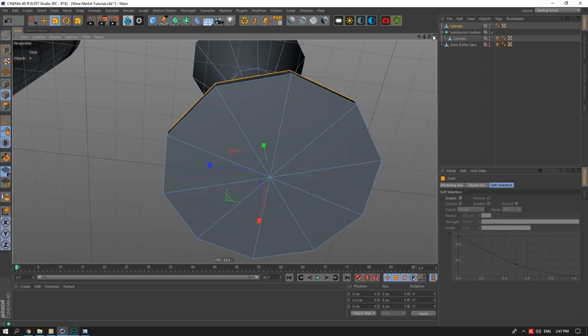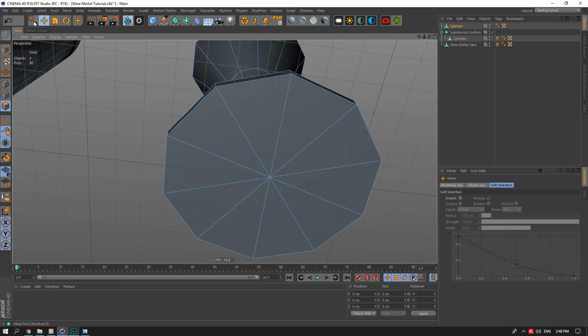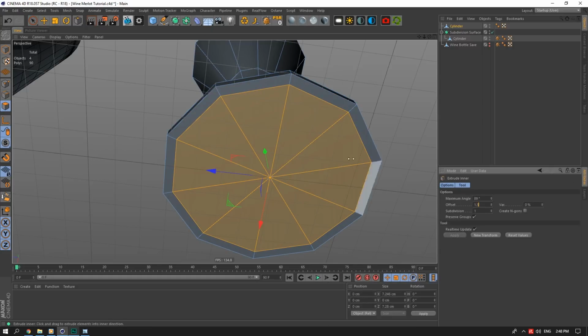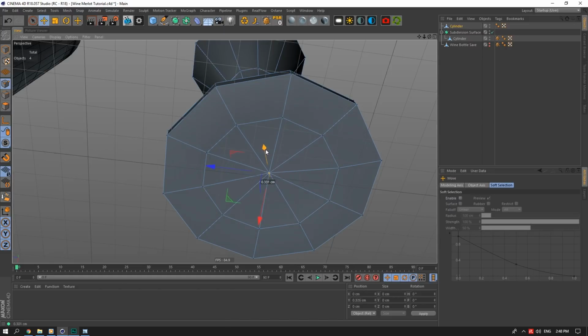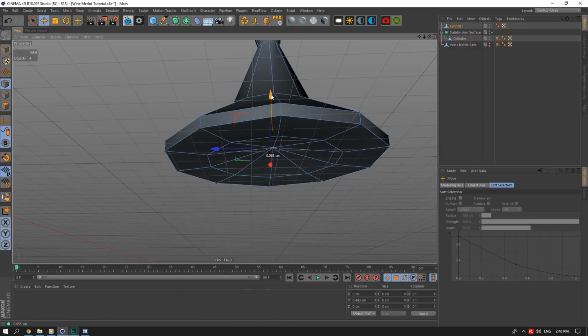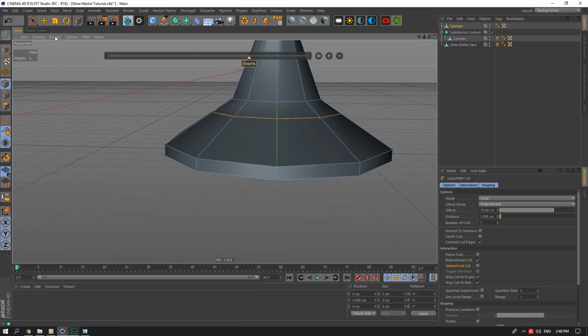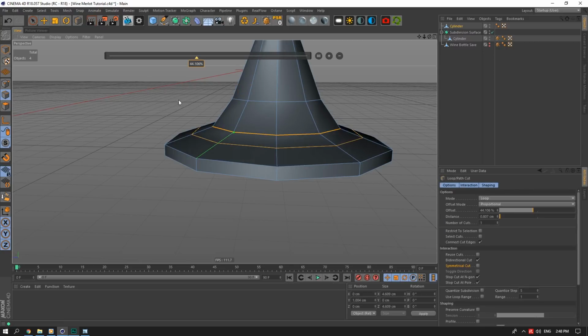So here I have a flat piece inside the glass, which is around 1.5 centimeters in height, in thickness. That's where the bump starts. So if I go here, 1.5, enter, and that's where the flat part ends, and then there's a slight nudge on the inside, so something like that would be good. And I'm just trying to figure out how to get this bump right. So I think we should have a line somewhere there, and then if I push this down and then put another line here, that will be where the bump is.